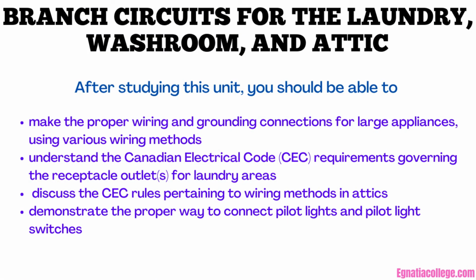After studying this unit, you should be able to make the proper wiring and grounding connections for large appliances, using various wiring methods. Understand the Canadian Electrical Code (CEC) requirements governing the receptacle outlets for laundry areas. Discuss the CEC rules pertaining to wiring methods in attics. Demonstrate the proper way to connect pilot lights and pilot light switches.